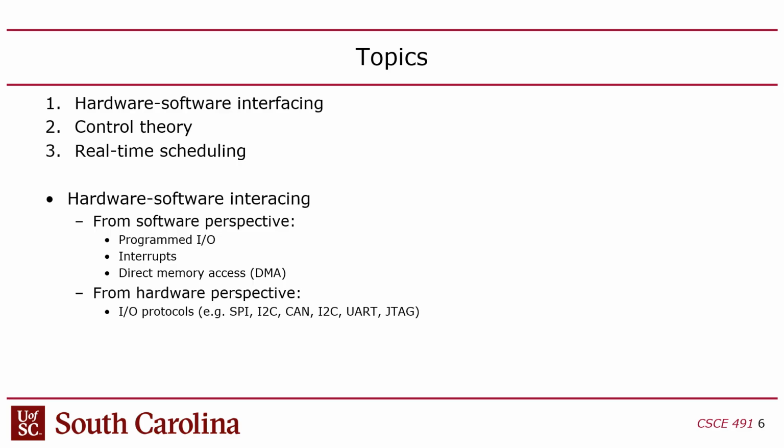So each I/O device has these control and status registers, which is kind of an antiquated term because originally a control register is something that you would write to with a store instruction, and it would be an output to the device. And a status register would be something that you would read from, you'd load from, and it would be an input from the device, right?